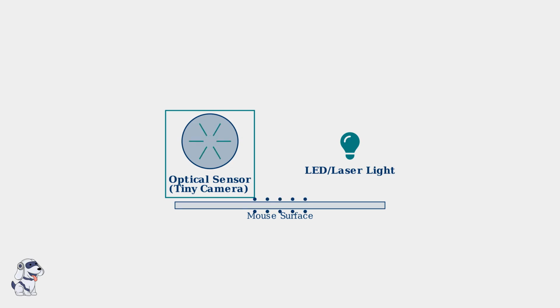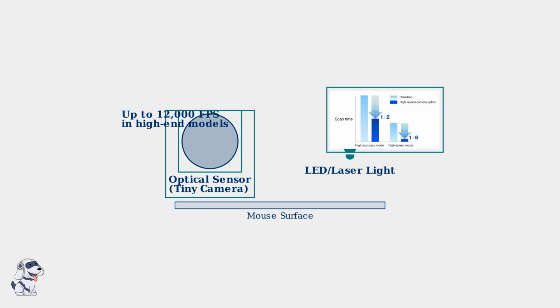The optical sensor continuously captures rapid images of this illuminated surface. Each image shows the texture details, which change as the mouse moves. By comparing these images frame by frame, the mouse calculates how far and in which direction it has moved. In high-end models, this happens at an astonishing rate, up to 12,000 frames per second. This extreme speed ensures precise tracking even during fast movements, making the mouse incredibly responsive for gaming or detailed work.